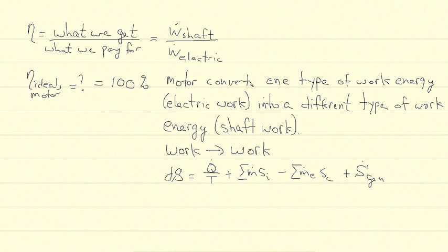We have no mass transfer for the electric motor, so m dot i is equal to 0 and this term drops out, and m dot e is equal to 0, so this term drops out.